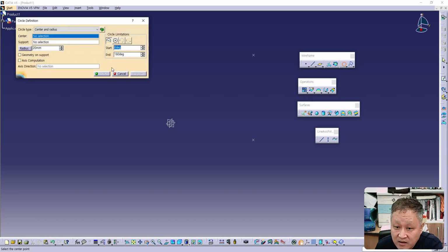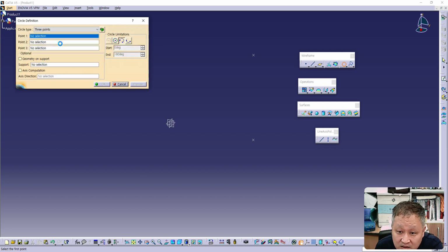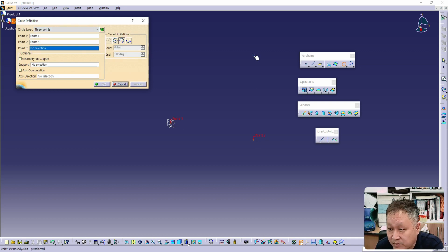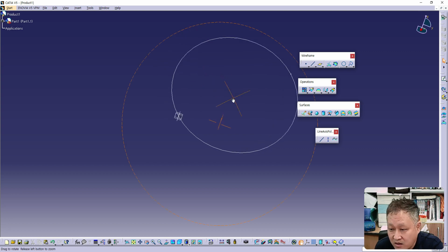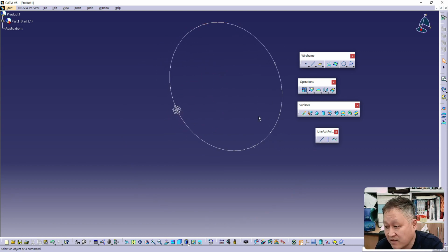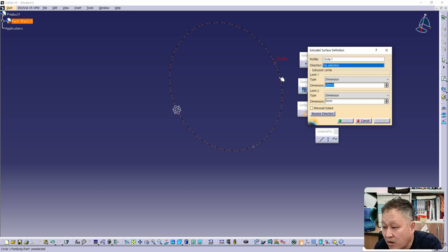In the case of a circle, if you select the 3 point menu, then with the 3 points selected previously, we can make some circle like here. And if you generate a circle, you can extrude it, then a cylinder can be made like here. These are some cases.